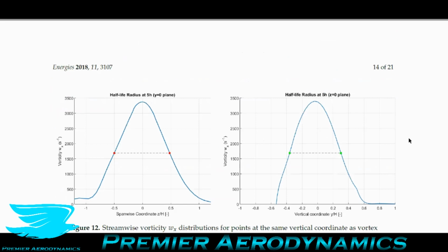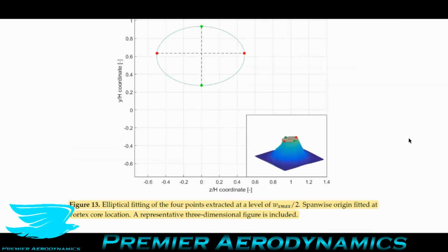A better way, I think, is by simply determining the area of the vortex that it takes up based on the vorticity equaling 0. That's the boundary. And then you find that area, and then you find the corresponding radius to a circle that would give you that area. And you say that's the average radius. Alternatively, you can always just find the average radius through a much simpler method, where you find the center of the vortex given the maximum vorticity. Then you find a line where the vorticity is 0, and then you find all the distances to that line around in a 360-degree rotation, and then you find the average radius.